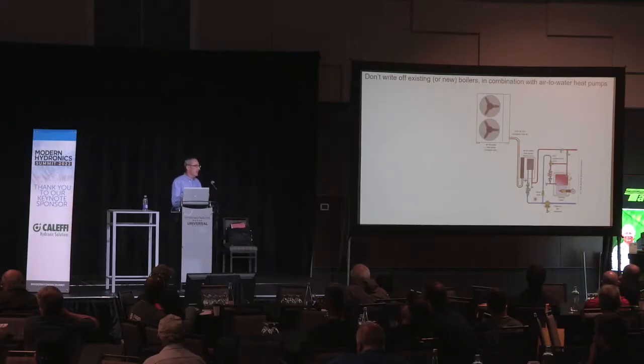Another thing to keep in mind is that we have thousands, probably tens of thousands, of cast iron boilers in the market. They have operated for years, maybe on baseboard systems where the water temperatures have been relatively high, 160, 180, maybe even a little higher. They're above the dew point of the flue gases the vast majority of their operating hours, so they don't experience what I refer to as sustained flue gas condensation. You might get a little intermittent flue gas condensation from a cold start, but they aren't operating hour after hour in a condensing mode of operation.